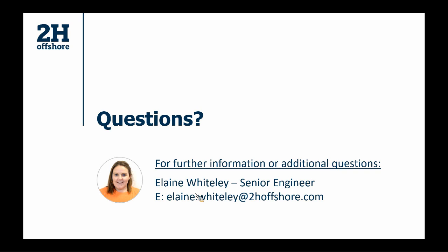Another question on slide 14 specifically, can we increase the number of centralizers to have better fatigue life? Yeah, so typically if you've got a larger number of guides, and especially if you have a tight centralization, then you've got less room for lateral movement, so you would typically find that your fatigue damage would be reduced.